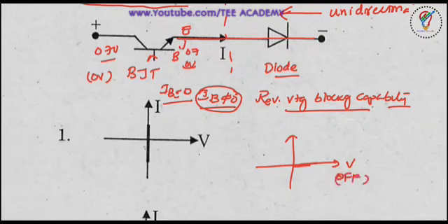Now if you give a base current, it starts conducting, and the current will have some maximum value, so it is in the on state. So the general characteristics of a BJT are like this, but it will not have reverse blocking capability. That means if you apply reverse voltage, it automatically gets damaged. But with the addition of this diode, you are giving some reverse blocking capability here.